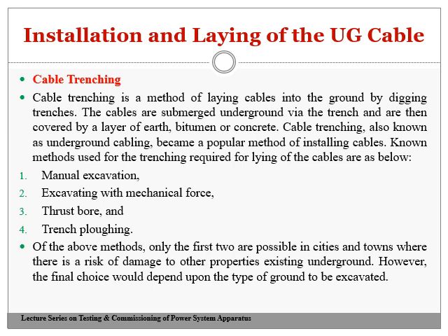It may be dug a little bit deeper, maybe 1 or 2 feet below the surface of the earth. It depends upon the number of cables which have to be laid down. If it's only one, then specific rules are followed, as we have discussed in the previous class. The cables are submerged underground via the trench and are then covered by a layer of earth, bitumen or concrete.